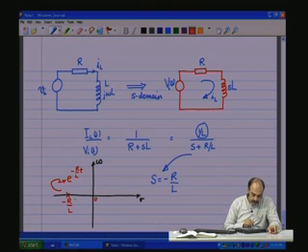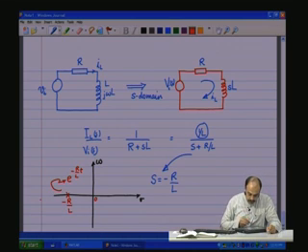In effect, L by R is becoming large, which means the time constant is expanding, becoming large, and takes a much longer time to decay till the point at this point 0, where either L is infinite or R is 0, this point where there is no decay. And as you start going away from 0, the L by R time constant starts decreasing and it starts decaying faster and faster. So, that is basically the meaning of that.